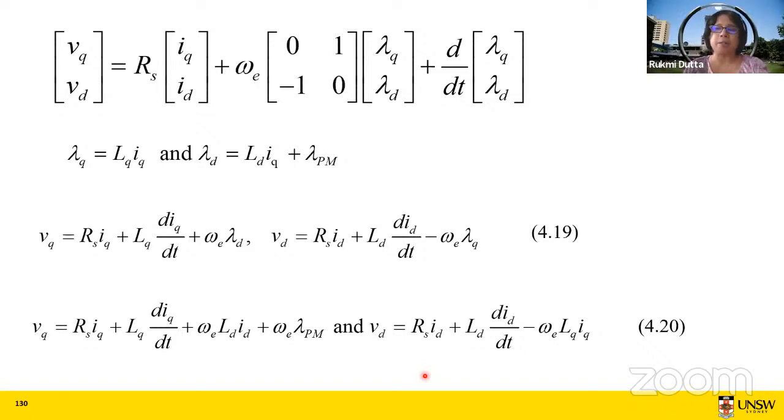So all that knowledge can now be brought in here. We have an RL load kind of, and we have a DC motor, all quantities are DC. So we can apply that knowledge to our model and design classical PI controllers even for our motor.